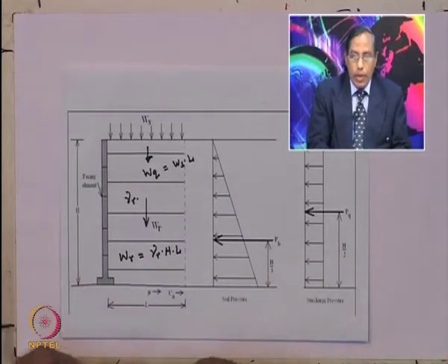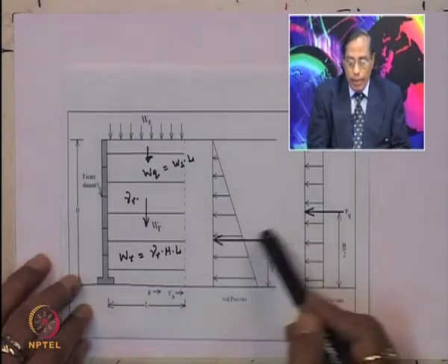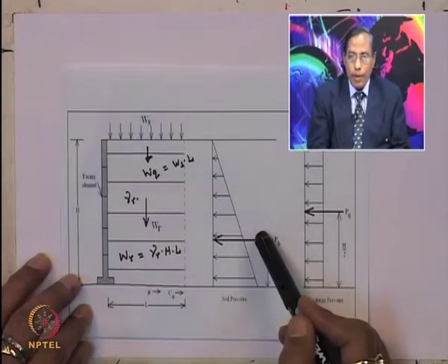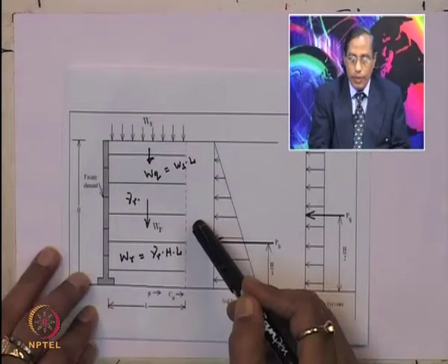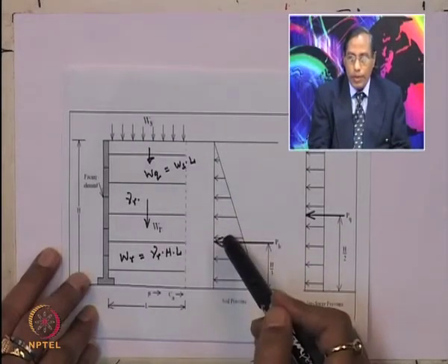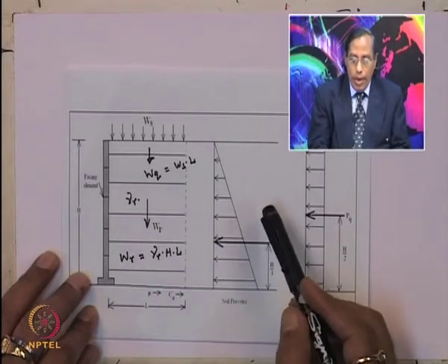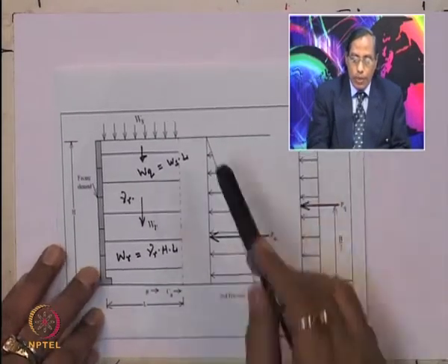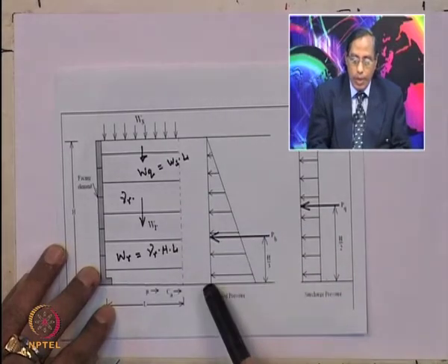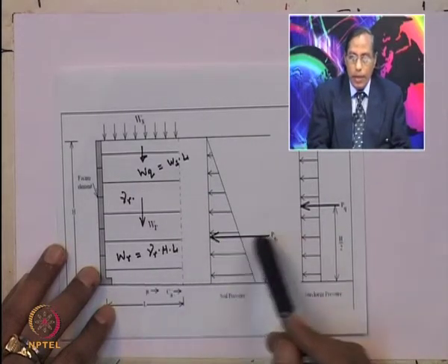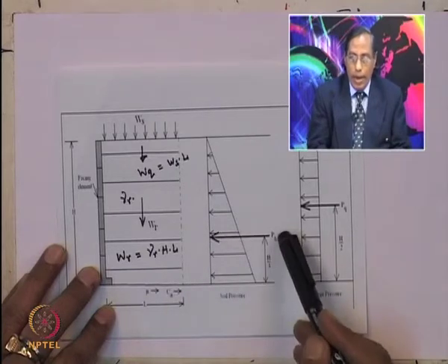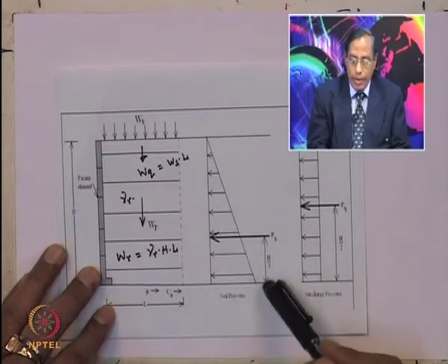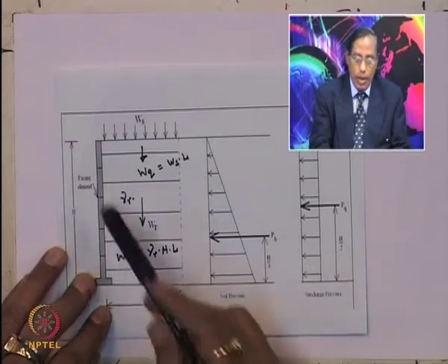And we see that there is a soil pressure. So, lateral soil pressure from the backfill, this is the backfill zone. There will be the lateral soil pressure on the backfill zone, and this soil pressure distribution will be triangular in pattern, and this PB is the lateral soil pressure from the backfill, which is acting at a distance of 1/3 of the height of the wall.